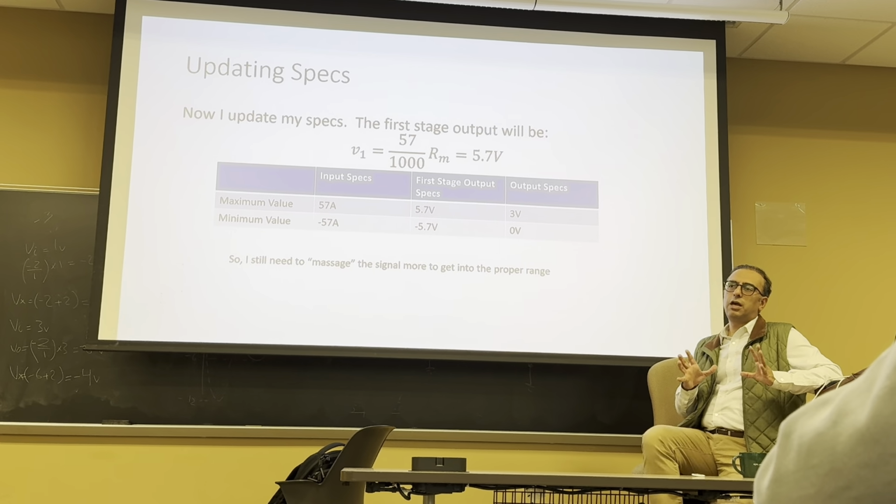I see. So that's why I'm saying the divergence starts to happen now. Copying becomes more challenging because the choices are different. If you pick, for whatever reason, this technology, which is one of the most accurate technologies in current measurement, you have to come up with a circuit to not only provide the conversion, but the transformation from a bipolar system to a unipolar one between 0 and 3 volts.